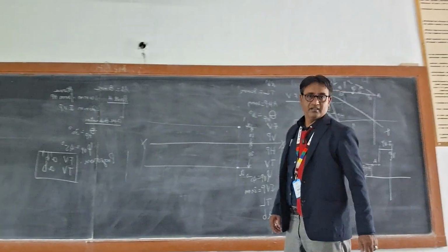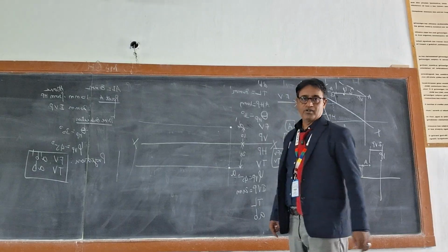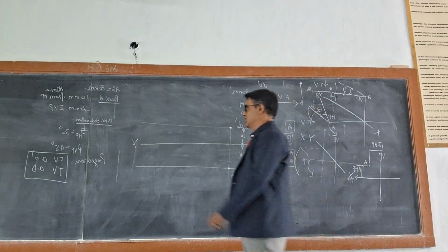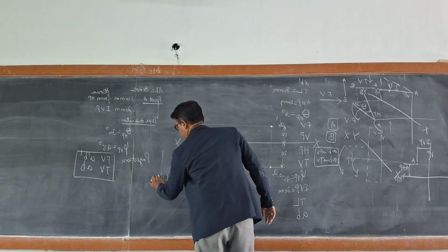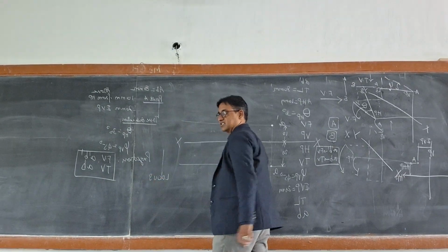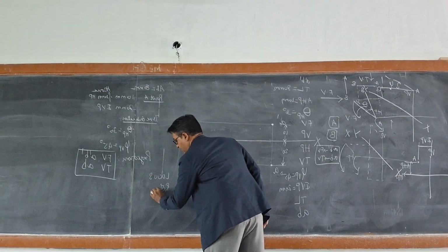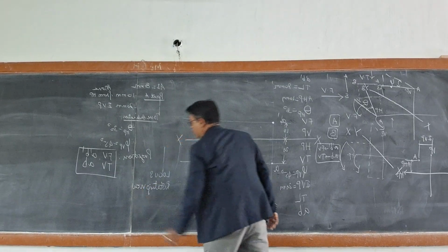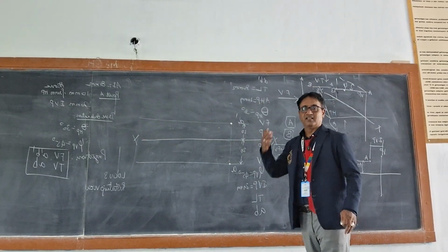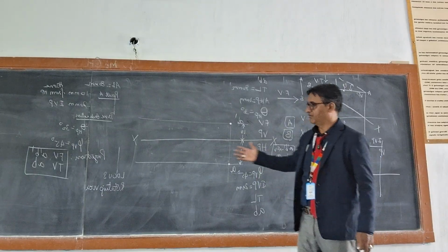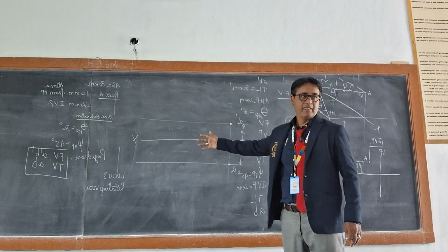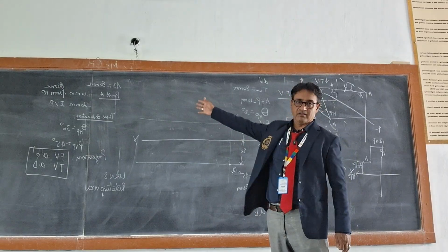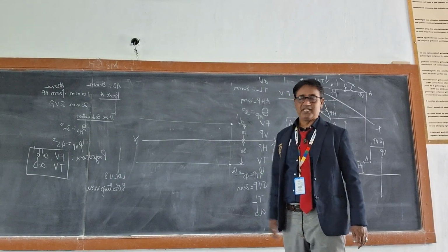Now in the projection of straight line problem, you are going to follow two important methodologies. One is locus and the next one is the rotating view method. Normally people say rotating line, but the correct way of defining this is rotating view, because you are going to rotate the view and find out the other end projectors, that is B dash and B.